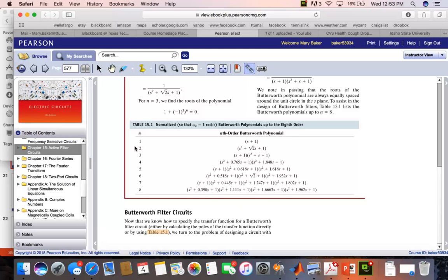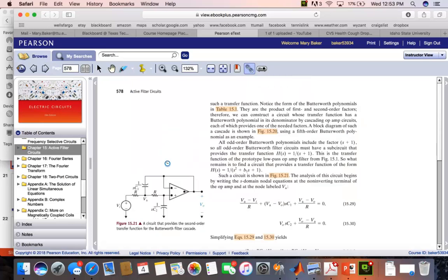And so what that circuit is doing is implementing a single one of these second order sections. Like in the fourth order, you have 2 second orders cascaded. In the sixth order, you would have 3 second orders cascaded. In the fifth order, you would have a regular op-amp filter, and then you'll have 2 second order filters cascaded. So you can see that basically what's changing is this middle number. So here's the circuit that is available to implement that.